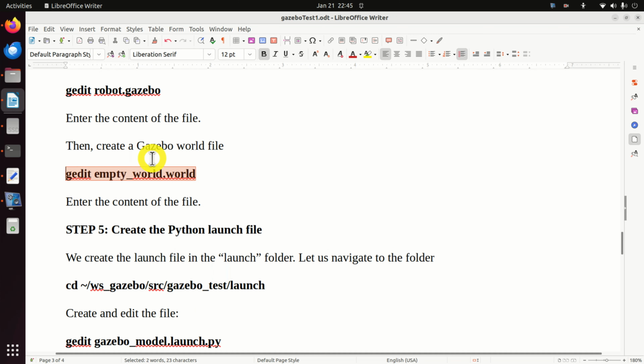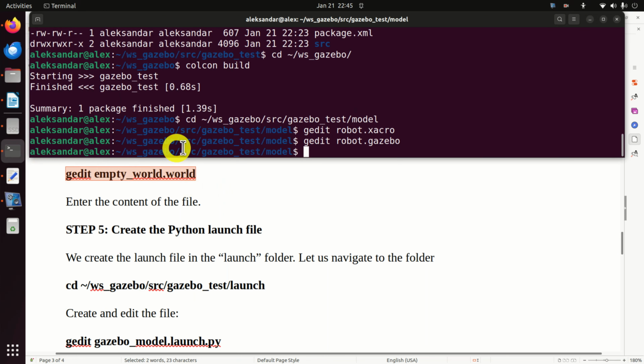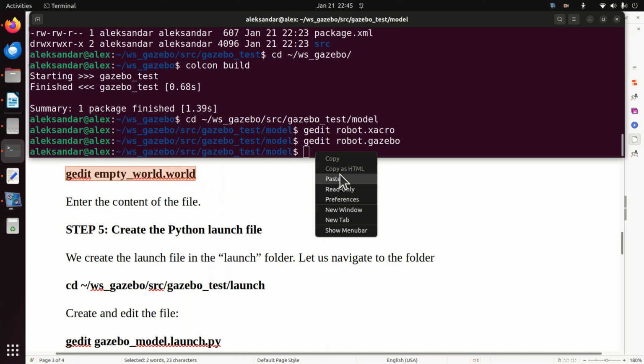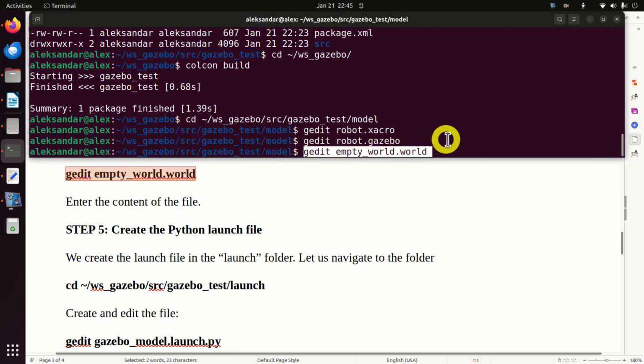The next step is to create a gazebo world file. Namely, any model that we create should be embedded in some world. World can be, for example, bus station, can be a simple plane, can be a desk, can be, for example, some company floor or something like that. And we need to specify the world. Over here we will define a simple empty world, since we don't want to blur the main ideas of this tutorial with too many modeling details.